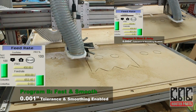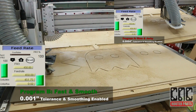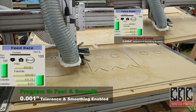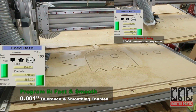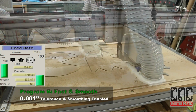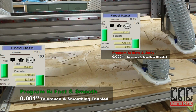This could be because you miscalculated your feed rate. However, in many cases, such as program A, it may well suggest that you have excessive data and would gain machine productivity from reducing it, either by cleaning up your project sketch or model and ensuring it doesn't have excessive sketch points or polylines that could be arcs, loosening the toolpath tolerance, or better yet, as we've shown here, by using smoothing to turn those linear moves into more efficient arc moves.